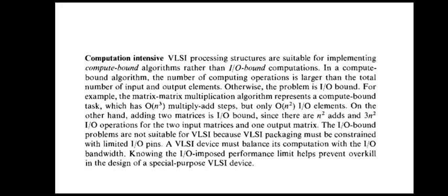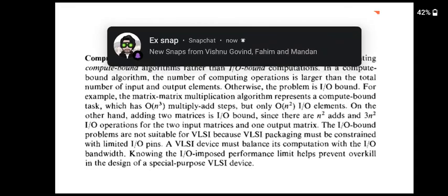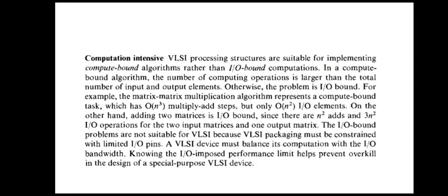The IO bound problems are not suitable for VLSI because VLSI packaging must be constrained with limited IO pins. A VLSI device must balance its computation with the IO bandwidth. Knowing the IO imposed performance limit helps prevent overkill in the design of special purpose VLSI devices.